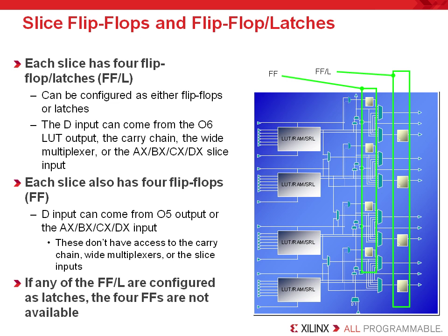Now, these limitations are not as big of a deal as you might think, however. In the end, if you're building lots of lower input functions that share inputs, as is required to have the 6-input LUT broken into 2 5-input LUTs, you should end up with the flip-flops being used extensively like this.